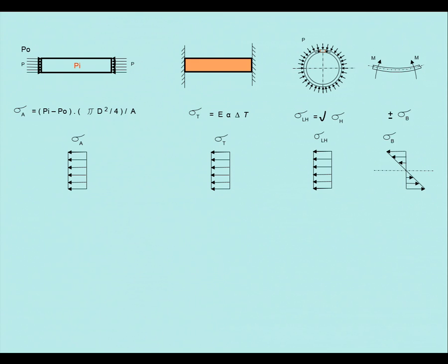So if you want to know the stress at the top of the pipe, that's the wrong way around. It should be that minus that plus that minus that, and then the same thing, add them up across the bottom. So you end up with two values of stress. When you've got that stress, that's the actual stress in your pipe. Oh, I've got my residual stress.